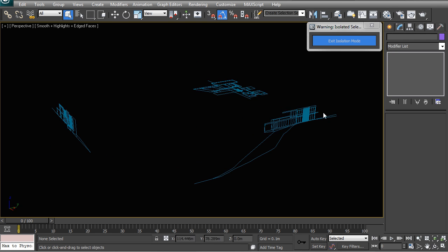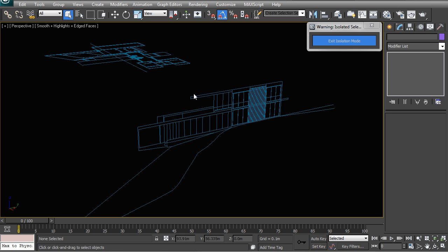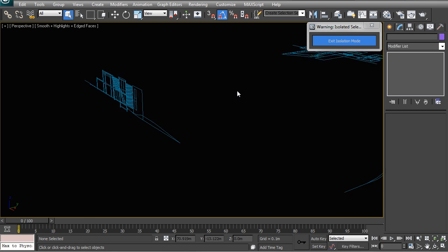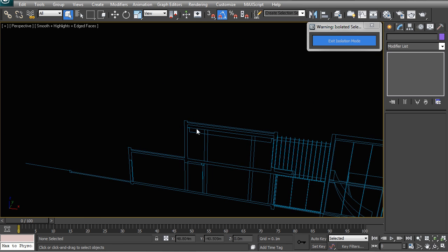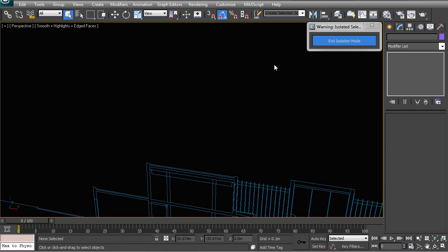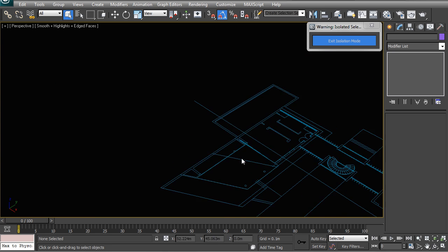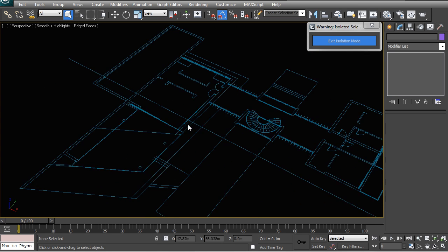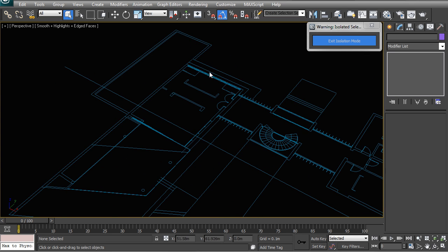In other words, you have some information for the roof on this side, so you can see this large overhanging lip over here. You can see in this section where the roof is as you cut through it. And in this plan, you have a line which I'm going to trace for you now, which is this line here, which shows you an edge of the roof above the floor plan. This is much more visible in your AutoCAD file, where it would be shown as a dotted dashed line indicating that something is happening above.